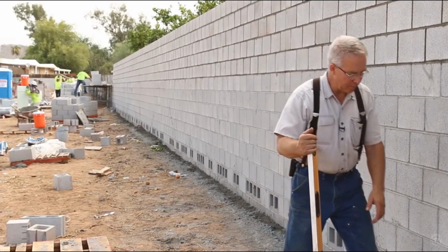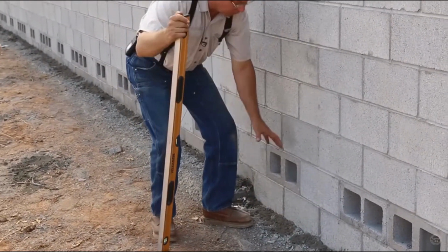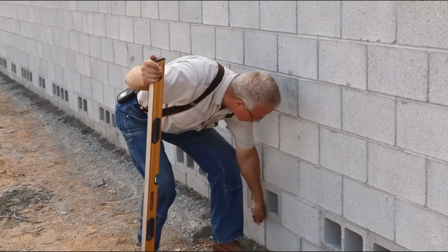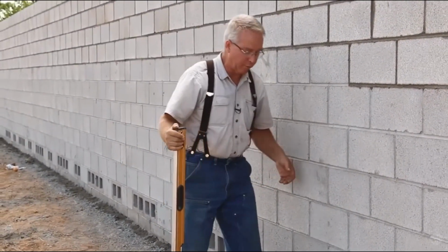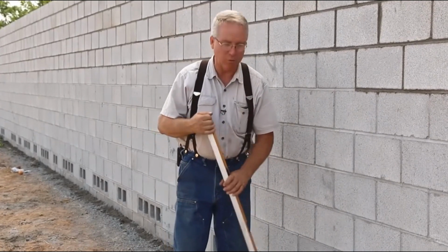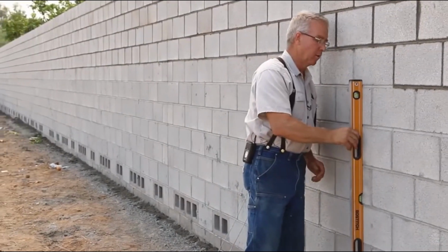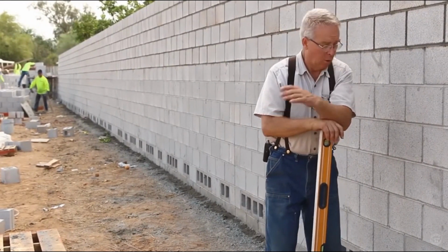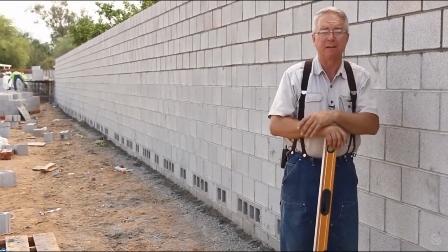Think of it. You're placing these blocks and the mud down at the height of the soles of your shoes, and then you've got to set them there to a string, get the head joints in, strike it off, and when you walk away, or when you start coming up with the next courses, you got to know for sure that thing is where it goes. Because if that thing's wrong, it's going to take you quite a distance to get the wall back to square, plumb, and true. So that first base course is painful. Once you start getting up about knee high and coming on up, it's just not bad.